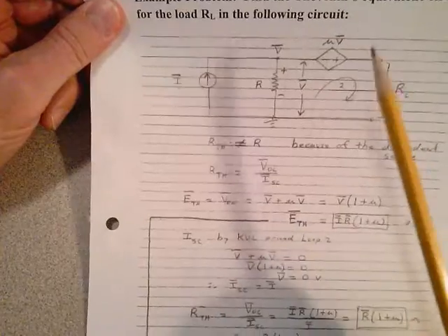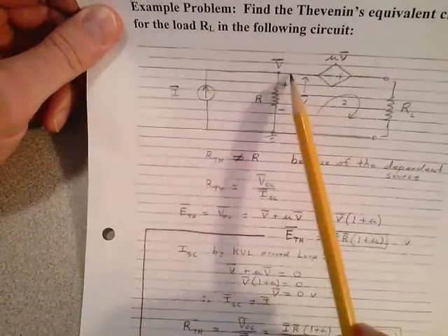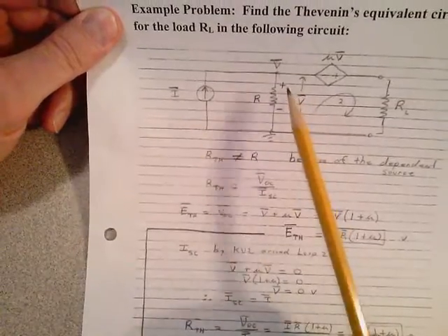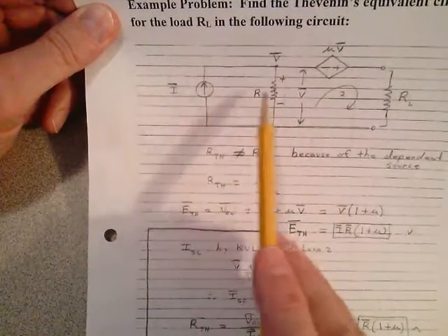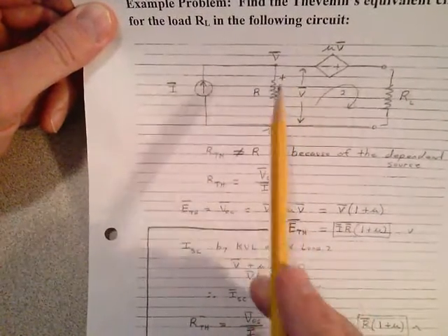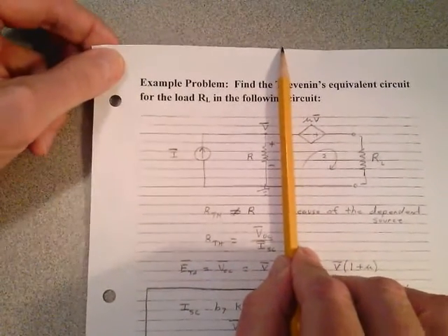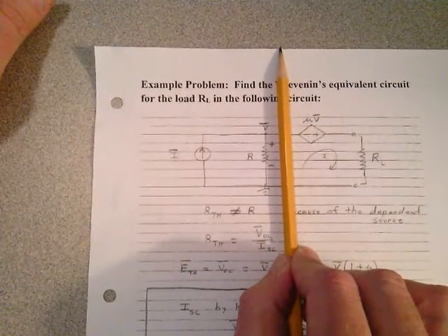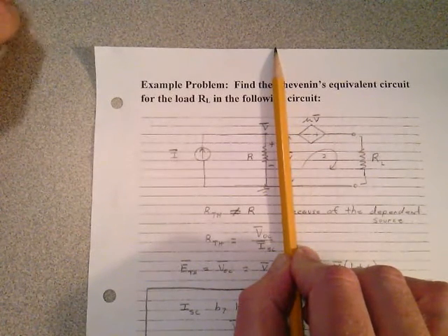Incidentally, one student may do it this way. Another student might say, well, before I analyze this circuit, I'm going to convert this current Norton equivalent to a Thevenin circuit on its own. So you can replace everything to the left of my pencil with a Thevenin voltage and a Thevenin resistance.